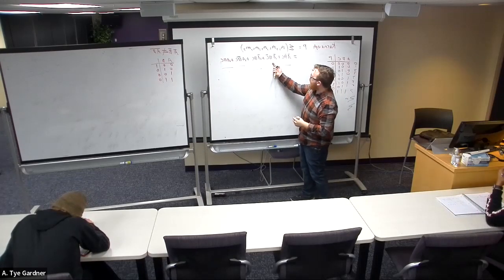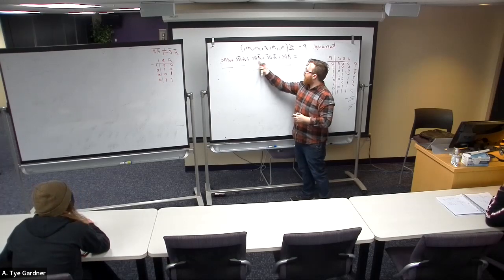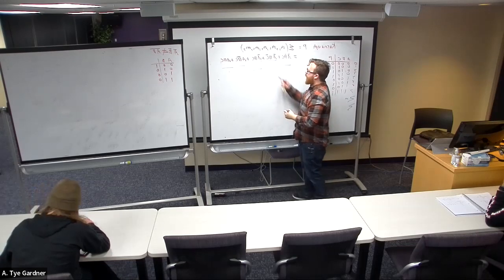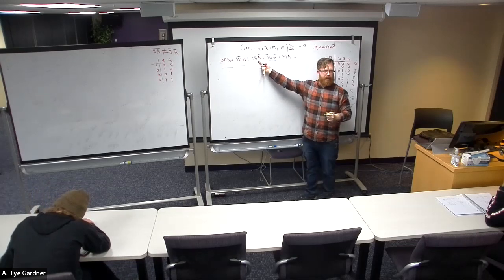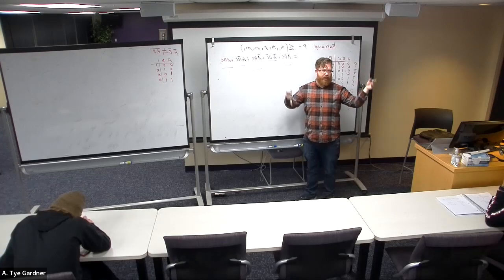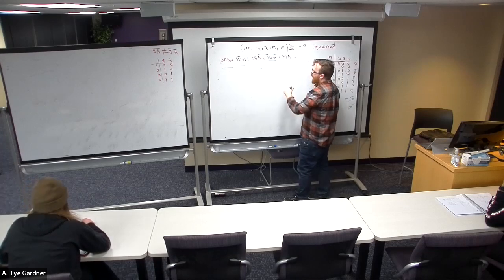And now I have this one. Do I have any that are not A, B, not C? So those two are the same. So that one and that one are the same, and I'm going to use that one twice, right? Because A or A is equal to A. We can add redundant terms. So I would just add an extra not A, B, C so that I could simplify.